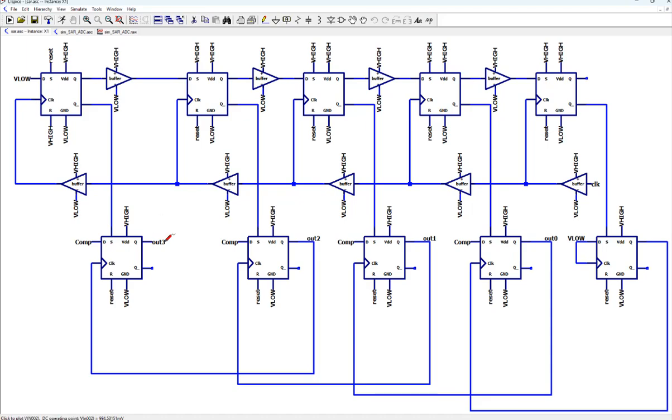So the sequencer on the top will shift that one to the right, right? And what's going to happen after that? Then it's going to set the second D flip-flop of the code register. Then what? You got a 1 here, right? And this one is being sent to here, forming a rising edge, which will register A3 to here. That's the first data to be registered over there.